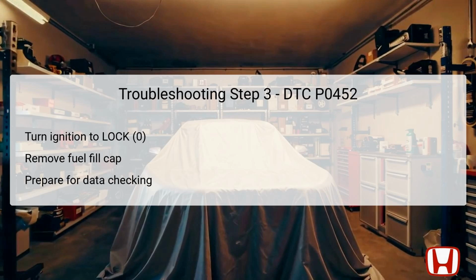This action is necessary for safety and to allow for the next diagnostic step, which involves removing the fuel fill cap. Removing the fuel fill cap is essential because it will normalize pressure readings and prepares the FTP sensor for accurate data collection. This step emphasizes ensuring that the fuel tank is vented properly before proceeding further with testing, as excess pressure or vacuum can yield faulty sensor readings. Ensuring these preliminary actions are executed correctly paves the way for more accurate diagnostic outcomes.